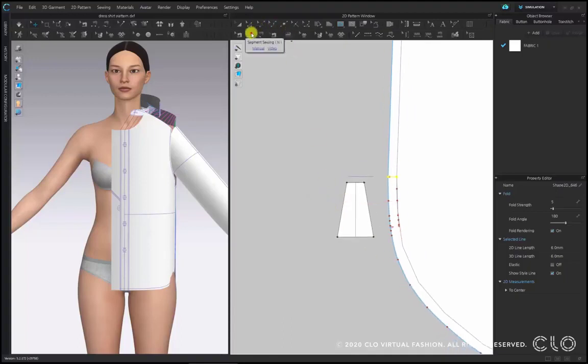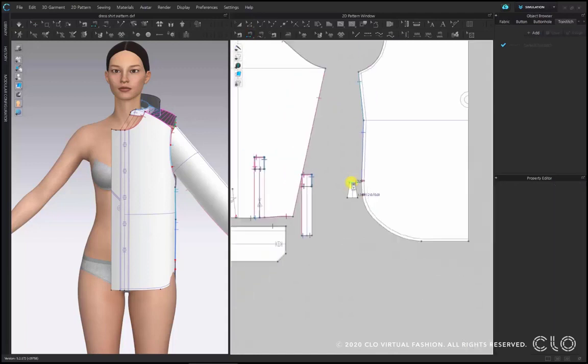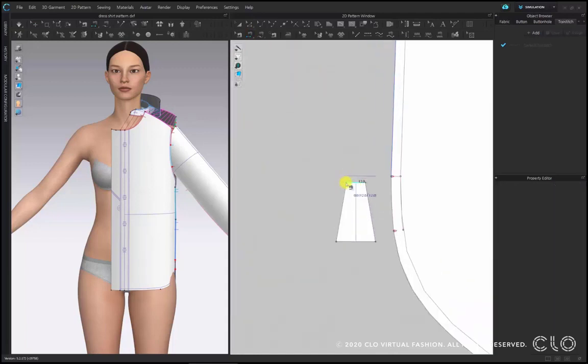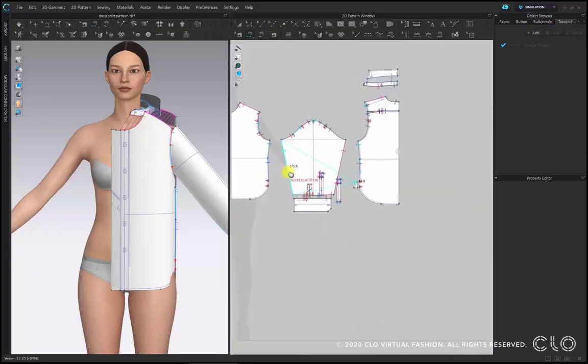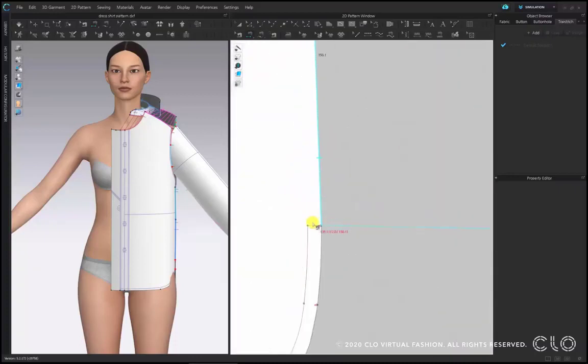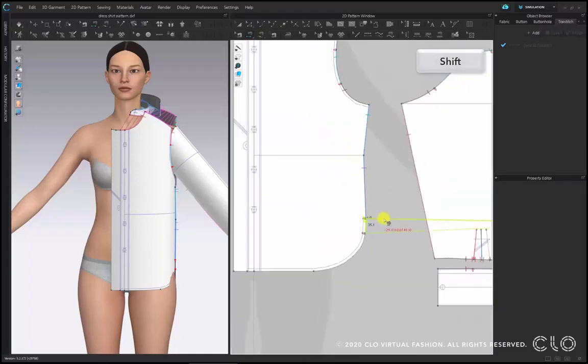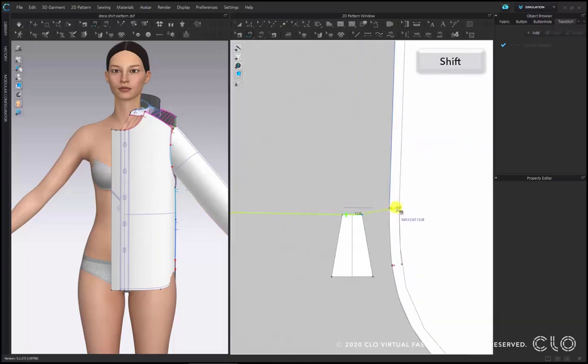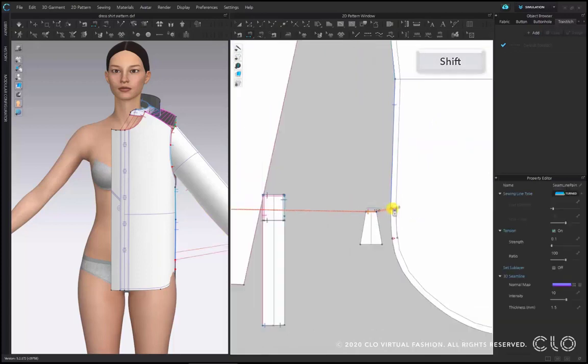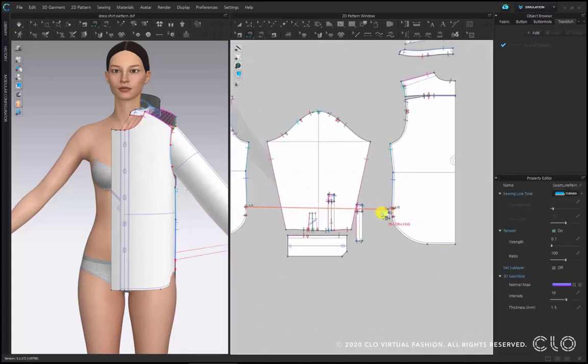Here I change to the segment sewing tool. Also here I will use the one-to-many sewing, so I pay attention. My sewing line notch is facing to the left, which means I need to start at the front. Press Shift, attach the first top part of the gusset, and then also the one at the back. Let go of Shift and have it connected.